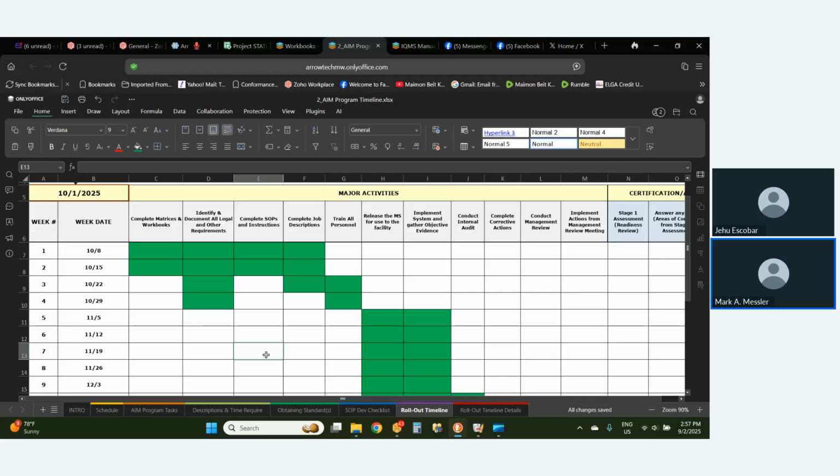Everybody thinks, well, I just throw some weights on there and see if it's right. No, it's not that. Depending on the size of it, you have to do it in quadrants, on an ascending scale, and on a descending scale. It's pretty complicated. Make sure you get somebody in there who is ISO 17025 certified to do scales.